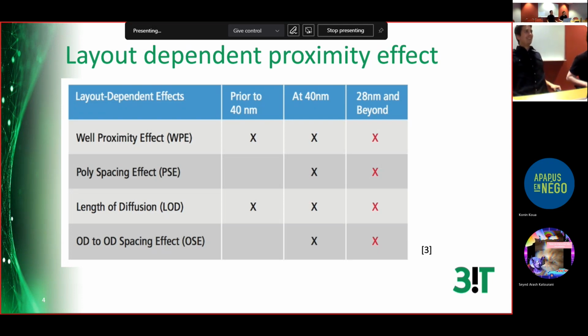You have to pay attention. When you talk about dummies, they are not just on the left and the right. Top and bottom also, you have to keep them far from you when you have lots of diffusion. For capacitors and for resistors, you can use dummies. You must use them if matching is important, even for capacitors. For resistors, maybe it's not needed.